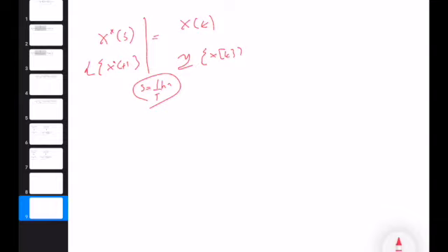Now this is very powerful for us, which says that maybe we can do our computations and analysis in the Laplace or s domain as much as possible. We can even design controllers in the s domain, then we can emulate them in the z domain by using this simple change of coordinates, right? So x of z, and we know that this is equal to the sum from k equals 0 to infinity of x_k z to the power minus k.